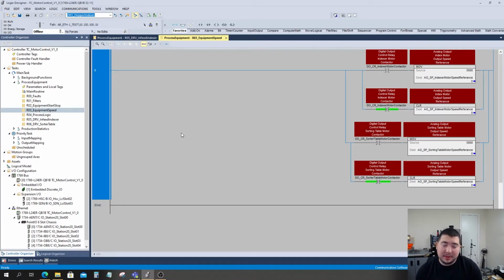The primary explanation that I've heard is that because scaling is handled in the card itself, that's why it wasn't added into RSLogix 5000, because the primary use for the SCP instruction was to scale your engineering units with your actual analog units to make it easier for that correlation. However, in my case, and I imagine many others, the SCP function wasn't just used for scaling the output card value. It was also used to scale various parameters or values within the program for various other logical operations.